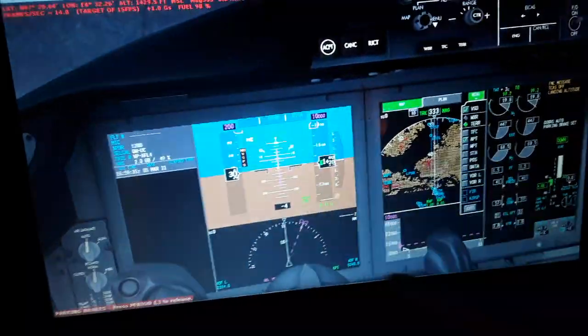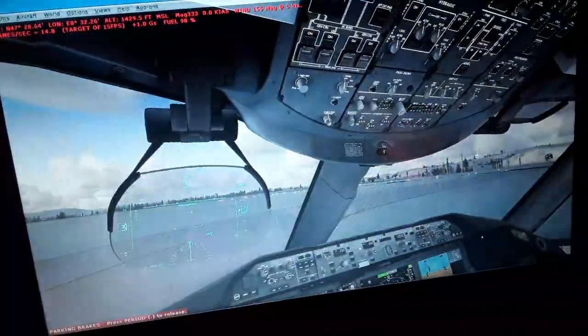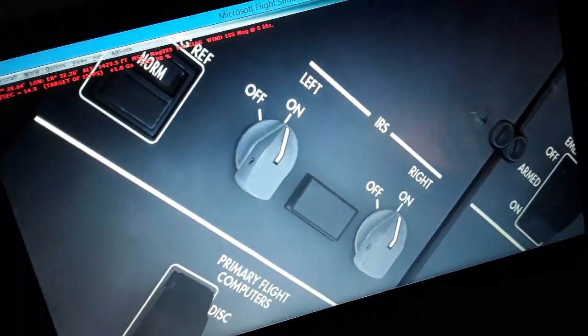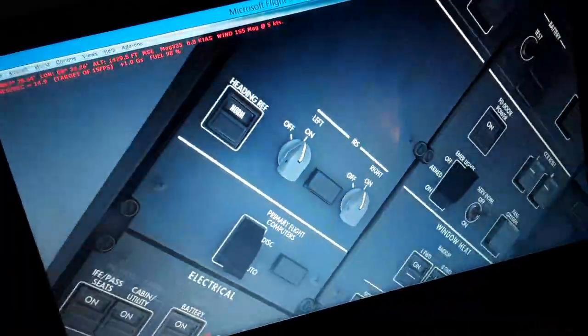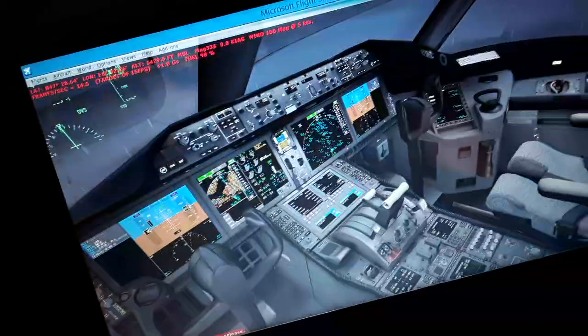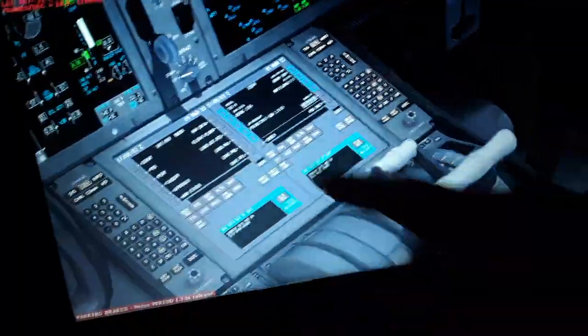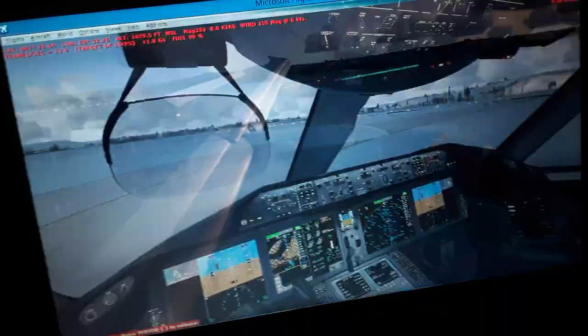So this is all the air data. Also the laser gyroscopes, gyroscopic acceleration, deceleration of the artificial horizon. This is calculated with laser gyroscopes. So this is the air data computer that is doing all these things. Also inertial alignment, you will see later the GPS position. All this is done from the air data computer. Airspeed, altitude. So you can set the inertial reference position over here later if you need.